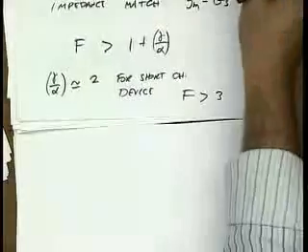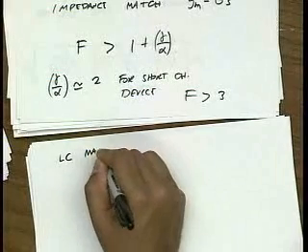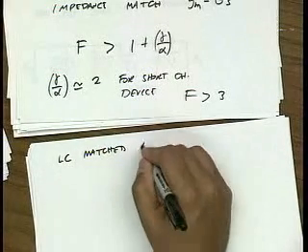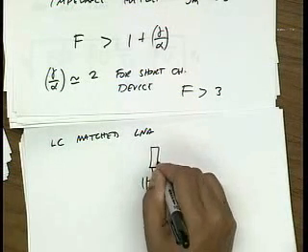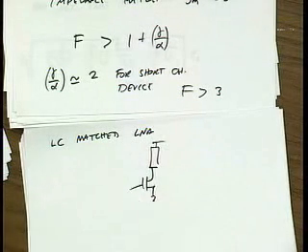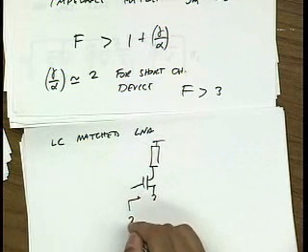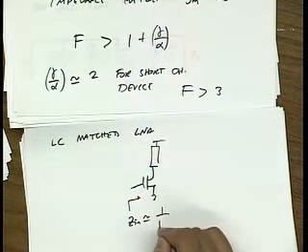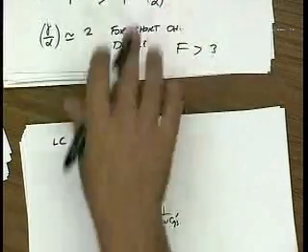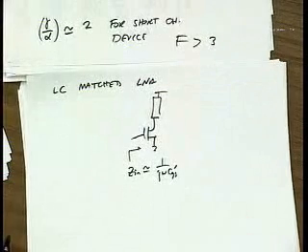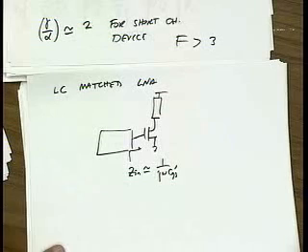All right, well, how about using matching networks? So an LC matched LNA. Again, we go back to this nice common source amplifier, and we say, okay, it has a really good noise performance, but basically Z in is roughly 1 over j omega CGS prime, and that's not good. It's not a power match. So what I'd like to do is put in a matching network here.